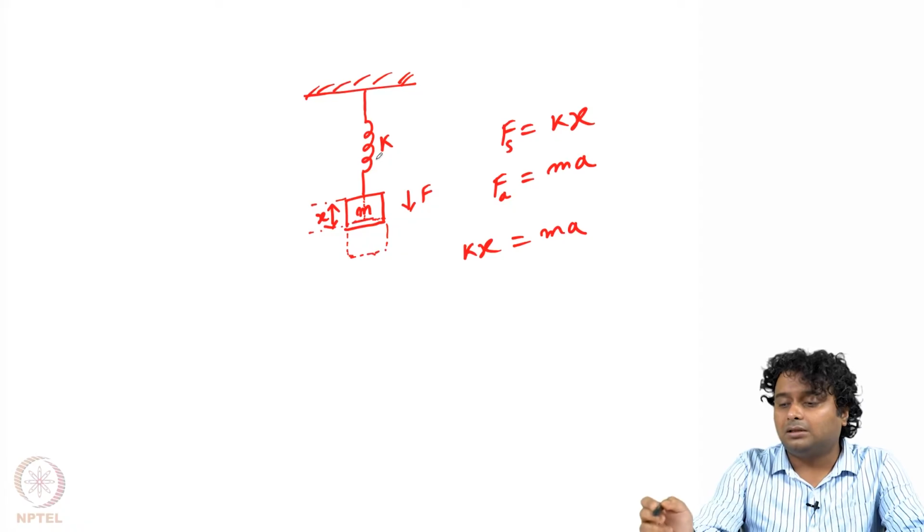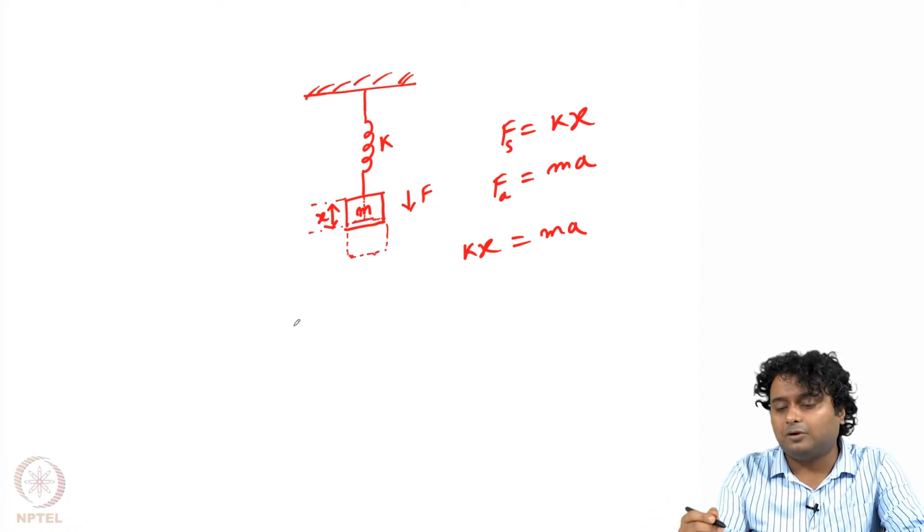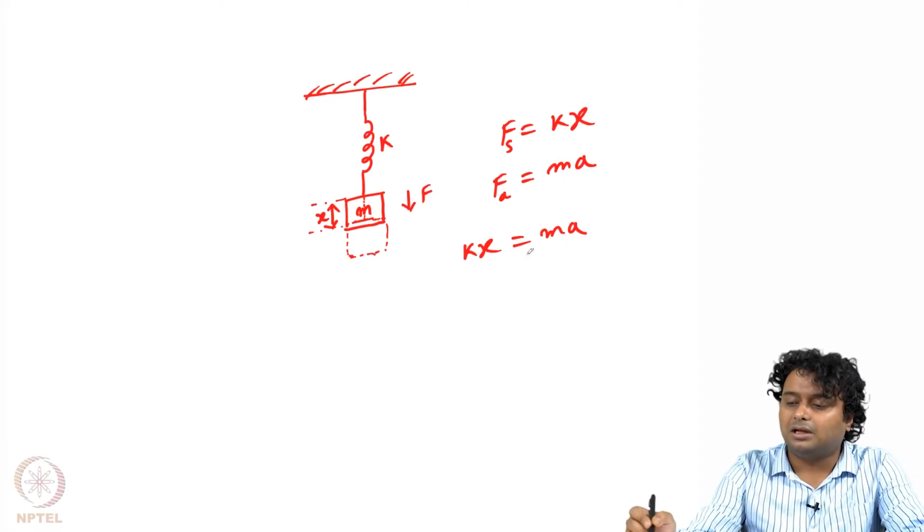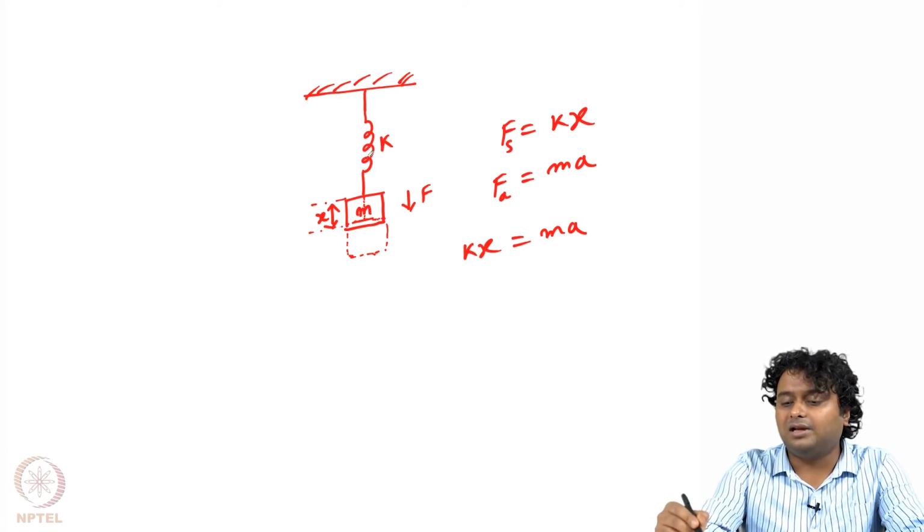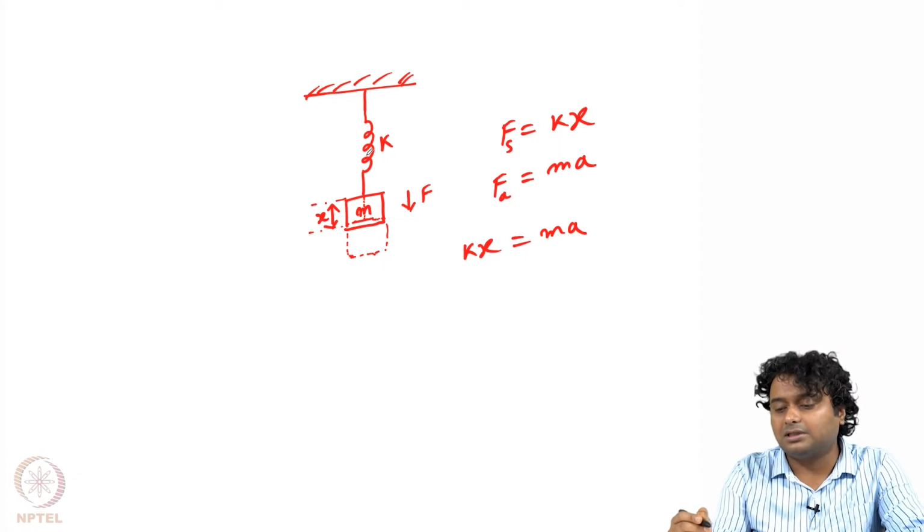So how can we measure? This is the same phenomenon we have been discussing from module 1 itself, right, that if we apply some amount of force, then there is a deflection, then we can measure the deflection, and accordingly we can measure how much is the force or the acceleration. So here also this is the deflection of the spring. In our case, while using some kind of sensor, this deflection will be of that particular membrane or cantilever, and accordingly we can measure the acceleration.